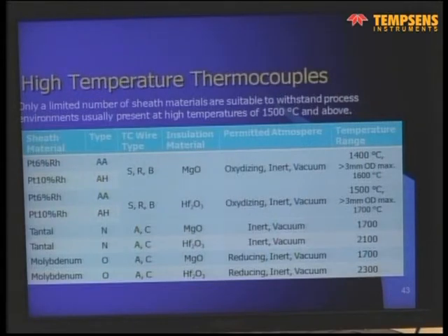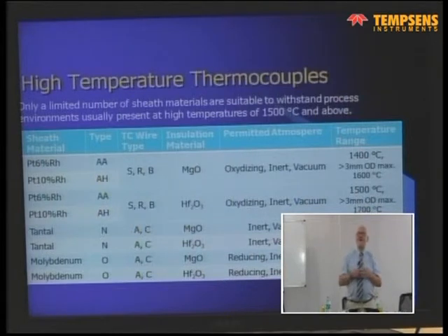because when you have particles below 5 microns in size, you can have them in your lung, and beryllium oxide inside your lung is hazardous because of cancer. So mostly it is prohibited. So magnesium oxide or even hafnium oxide is recommended for such applications. Both have no effect on your body. You can eat it, it's no problem. It comes out as it is, even in white.